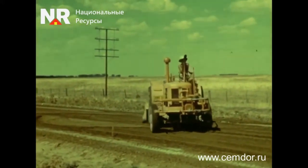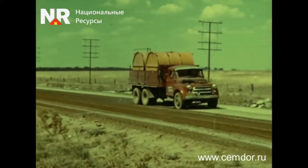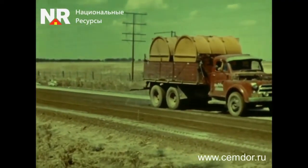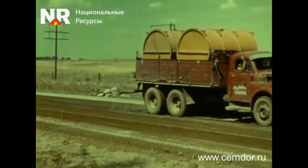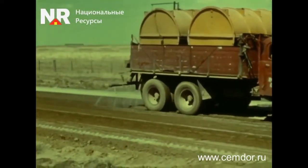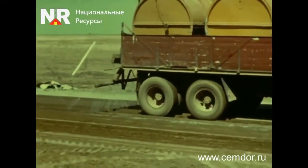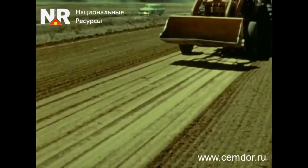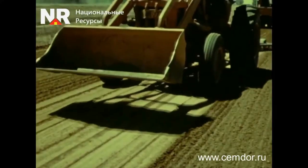During this operation, the moisture content of the mixture is maintained by distributing water from the tank truck. In this case, to prevent the formation of irregularities on the compacted surface, cultivation is performed before the rollers pass.